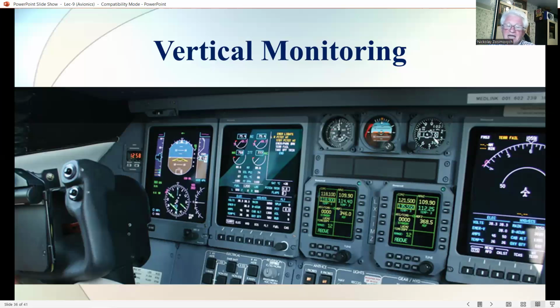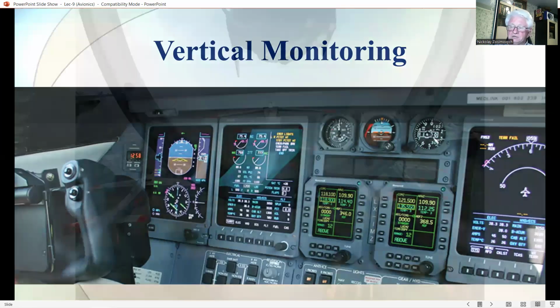However, any aircraft accelerations would result in the accelerometers defining a deflected or dynamic vertical, because the accelerometers are unable to distinguish between the gravity component and the acceleration component.